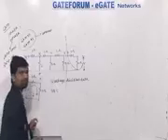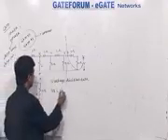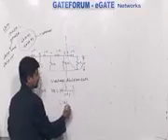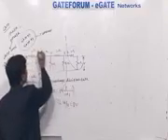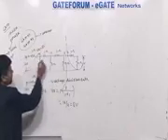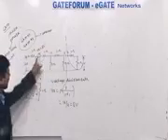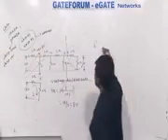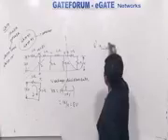What is Vx now? Vx is equal to 16 into 1 divided by 1 plus 1. 16 by 2, 8 volts. Now I got this potential Vx equal to 8 volts. Now let us forget about this circuit. I got the potential at X, which is equal to 8 volts. So the next step is that I can consider this point as Vx, 1 ohm.